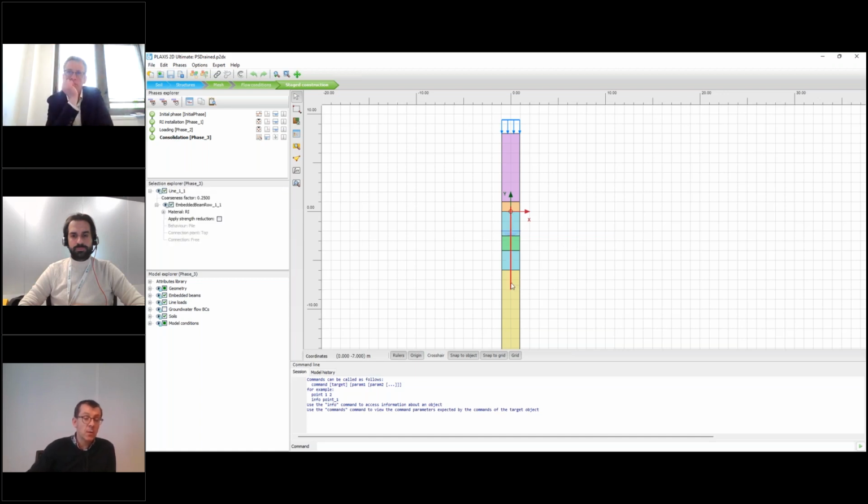And we will iterate over that model using trial and error until we are matching exactly the axis symmetrical model. Then we will consider the calibration to be efficient and achieved. And only then, using those parameters, we will move into the 2D embankment model as presented earlier.